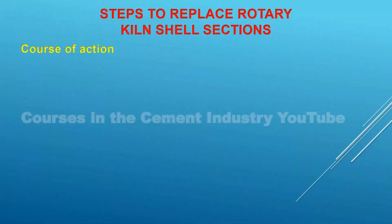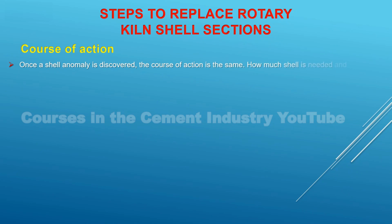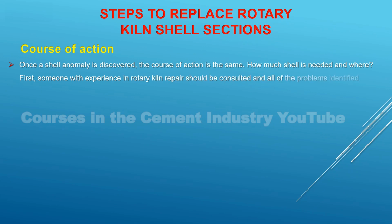Course of action. Once a shell anomaly is discovered, the course of action is the same. How much shell is needed and where? First, someone with experience in rotary kiln repair should be consulted, and all of the problems identified. From there, a rotary kiln shell run-out analysis will need to be performed.